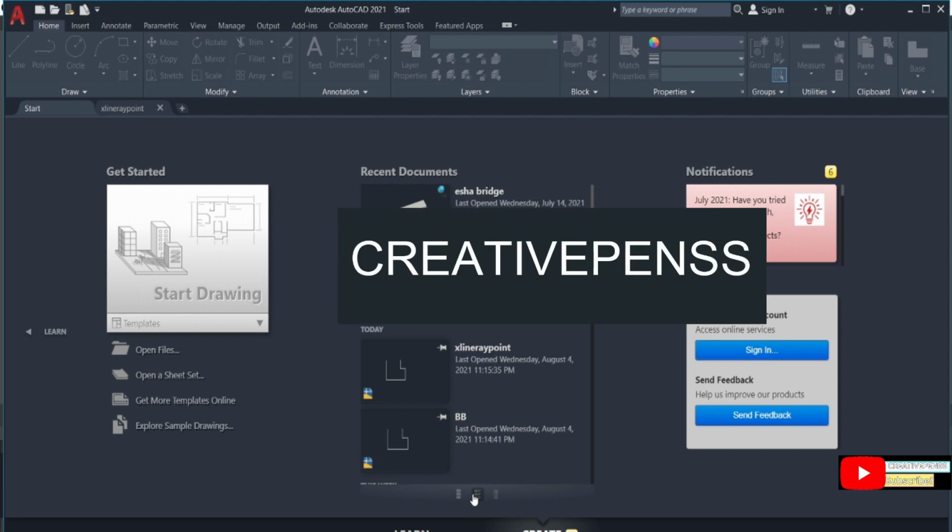In this video, I will explain how to use XLINE, Ray and Point. So let's start. Point, Ray and XLINE are typically used as temporary scaffolding in the drawing process. These project extended either a zero distance in the case of point, or infinite distances in the case of rays and XLINE. These objects are usually either erased or trimmed to suit the geometric situation.